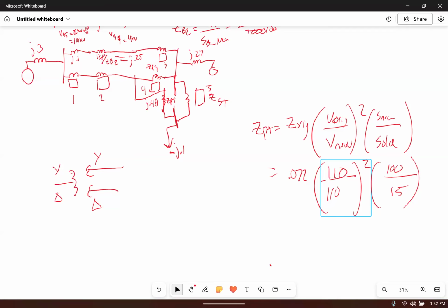I'm not sure you get the same answer. I don't think you actually would do that. I've never seen that done in industry. They just show it connected. There's no fictitious bus. There are actually 3 independent buses there. Well, anyway, I just know from doing PSSE, and I've done work in Power World, they'll do it. Power World makes that fictitious bus in the 3 winding transformers in its model.